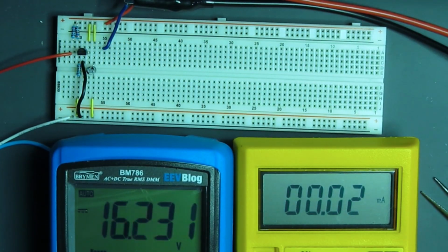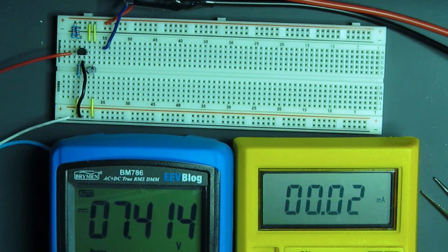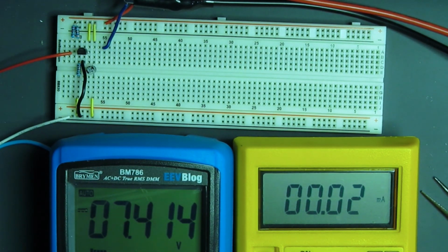When I hit the power, I see 7.414 volts, a little over 1% low. I didn't quite meet the 1% target, but I wasn't all that likely to with 1% resistors. I'll talk at the end about getting better precision. But right now it's time to test how the circuit performs under load.